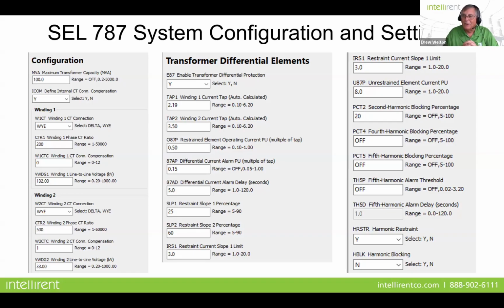The gentleman who was actually testing it for commissioning, once it was installed and ready to energize, took the information from the nameplate of the transformer, configured the test, and they didn't match. What happened was the engineer actually swapped the CT ratios from the primary and the secondary sides. And if you're just taking the settings out of the relay, it's ultimately going to pass. And if they didn't catch that during the commissioning process, that transformer relay would have obviously nuisance tripped during the